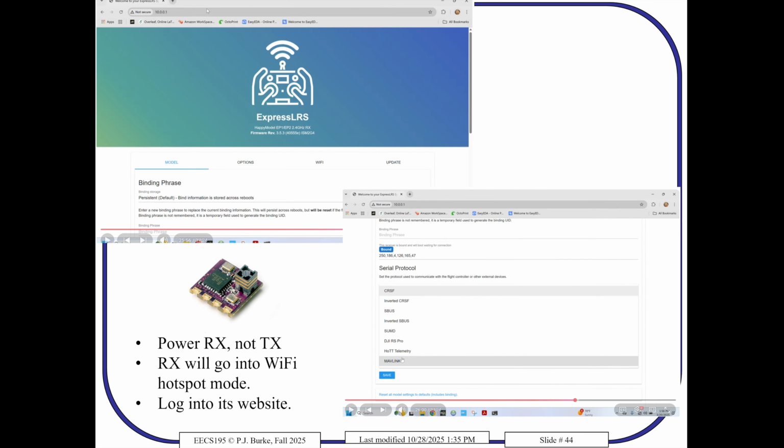In fact, you're going to need one of them to do the autonomous mission, because to do the autonomous mission, you have to put it in auto mode, and we only have 3 modes on the radio. So to put it in auto mode, you're going to have to connect the computer to it. Then once you put it in auto mode, it'll fly the autonomous mission. So you will need one of those 2.